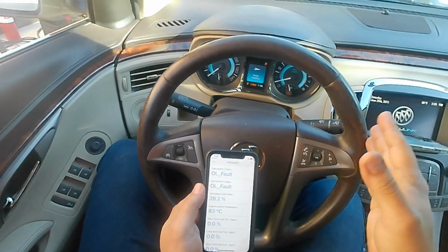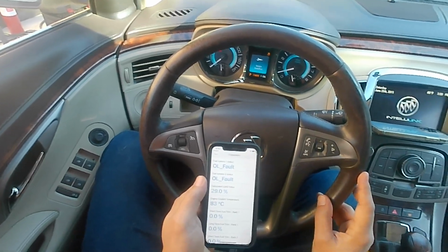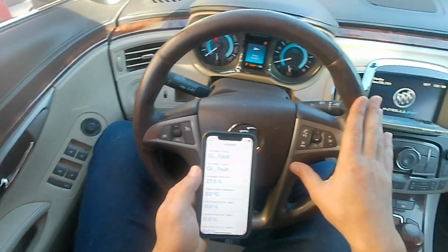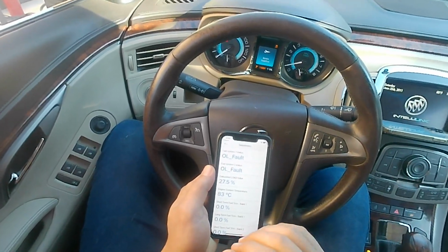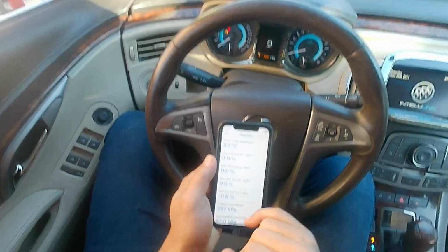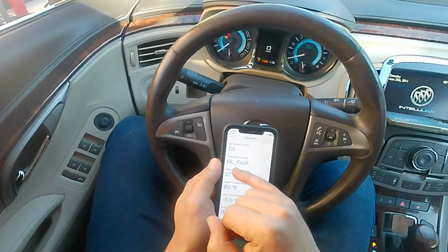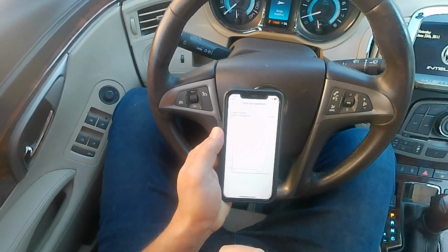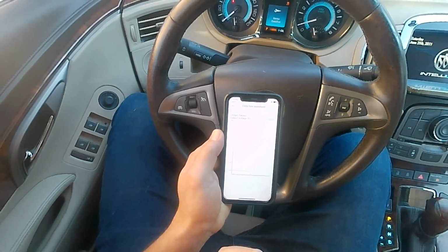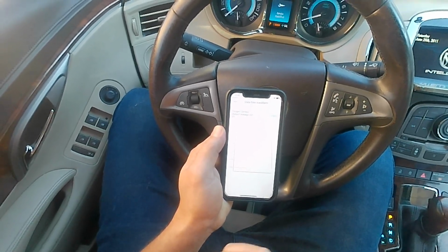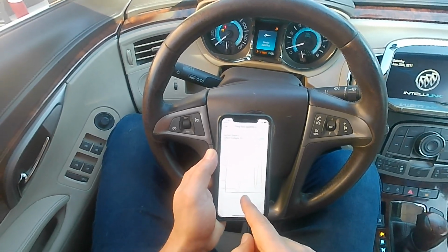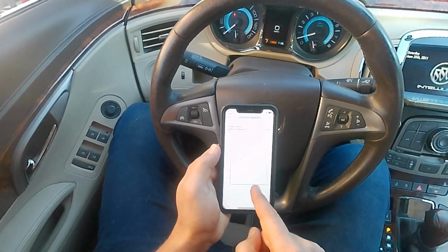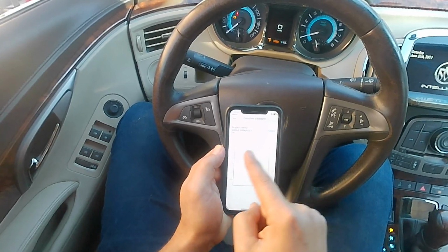The throttle body seal is not good, or you have any faulty oxygen sensors. So see, open loop at fault. Zoom into that data flow waveform and see if it's running steady, or are we getting any minus values. So as you can see, it's fluctuating, running straight.